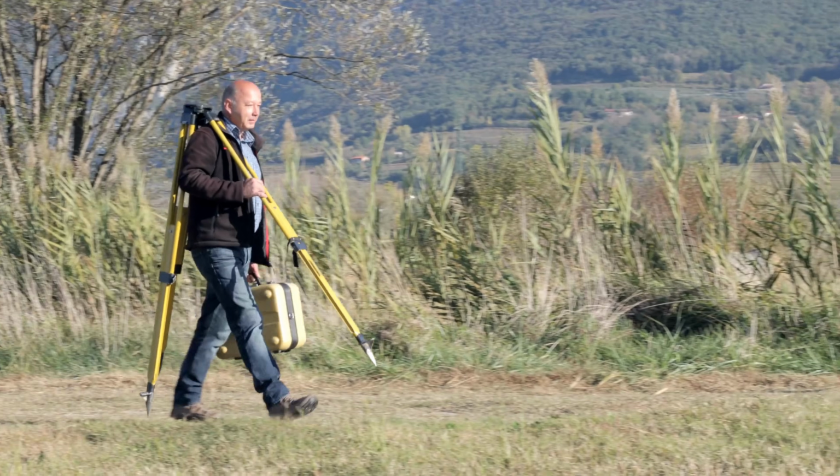The point of the land survey is to generate a map of the property that includes any boundaries, the topography, and any obstacles that need to be worked around. So the survey can include everything from the property lines to the setbacks that determine where the structures can be built on the lot, to existing utility line locations, trees, boulders, elevations, and any nearby structures on other lots. So the surveyor, they'll come out to your lot to physically map it out, and they'll also use a combination of county parcel records, utility records, and local building code to help generate a complete site map for your architect.